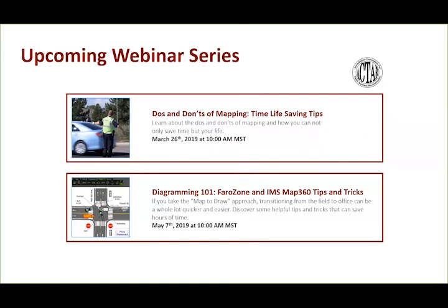If you're a government agency, then you're going to want to get a COA. The COA pre-approves those waivers ahead of time. If we get a deployment, we'll actually go on and file a drone NOTAM so that other aircraft know we're there. But we're still operating within the guidelines of our COA. But private sector, you're going to have to go through the normal FAA waiver procedure.